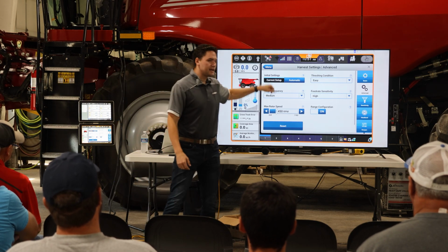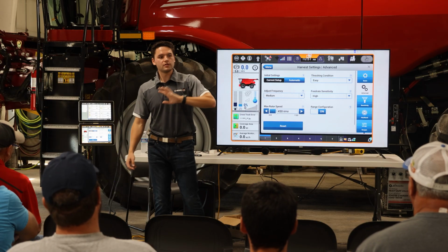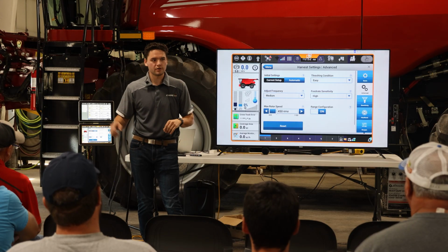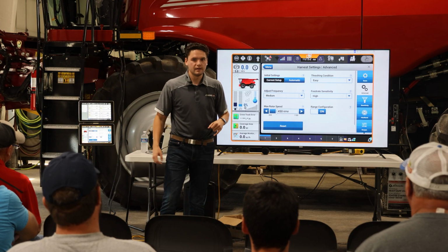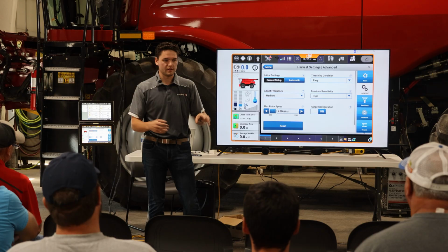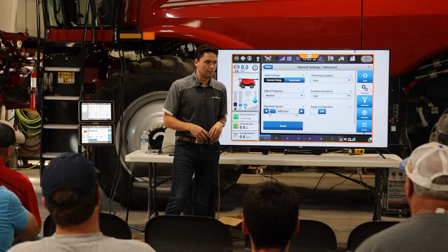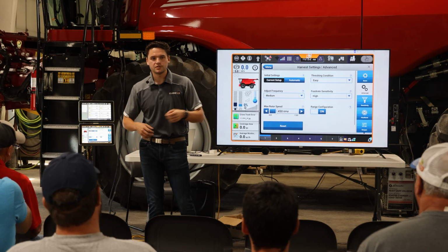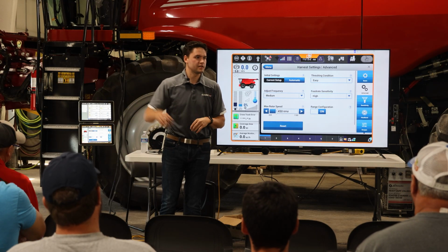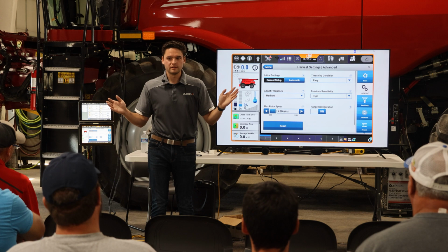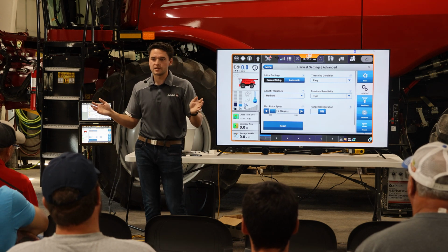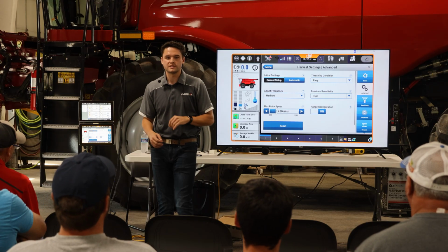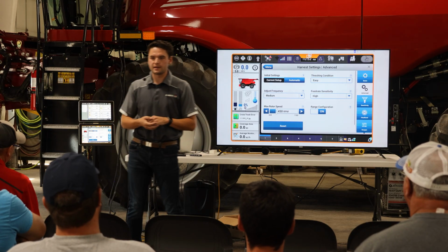If we had automatic selected, regardless of what work condition we were doing, regardless of how we had the machine set up, as soon as we turn automation on with automatic, it will change all the settings to how we think it should be running. So those are our automatic default settings. That's why maybe you've been running automation and I already had this thing running right, and as soon as I turned it on, it changed everything, and I don't like those numbers. The way you stop that from happening is making sure that it is on current setup versus automatic.